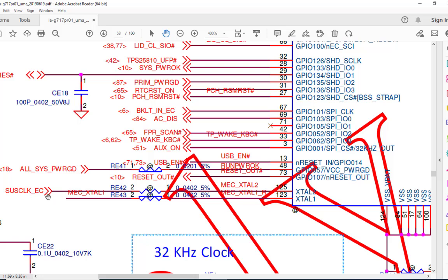So you have to check this SUS clock, and if this SUS clock is not coming, then you have to go to the processor and check the 32.7 kilohertz crystal, which generates the 32.7 kilohertz. And if you replace the crystal but still SUS clock is not generating, then you have to check the RTC reset and RTC battery. Okay, so once this clock generates at pin number 125 SUS clock, then you have to go for the next important signal, that is the power button.